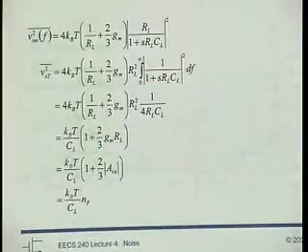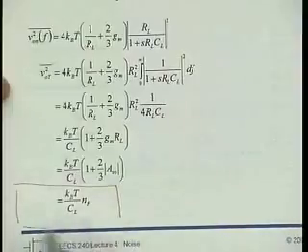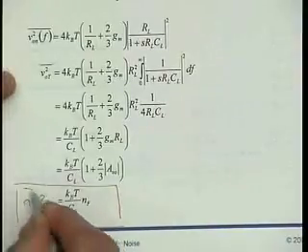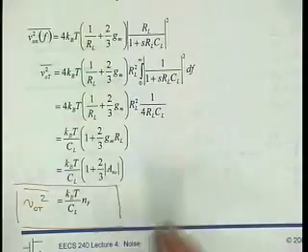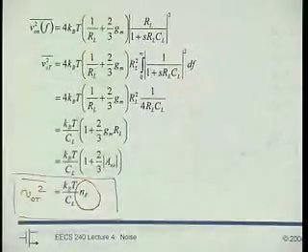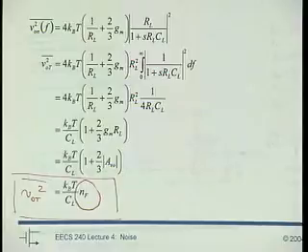And simplify this a few more times, and the result, again, is remarkable. VOT square: I have now a circuit that, okay, is not very complicated, but a little bit more complicated, and the result again is kT on C times a factor, and I usually call this factor the noise factor, sort of the noise penalty. Apparently, if I just use a switch and the capacitor, I just get kT on C. If I add an entire amplifier to the picture and other stuff, then that also produces noise. Then the end result is still going to be kT on C times some factor, a penalty factor for having put additional junk there.